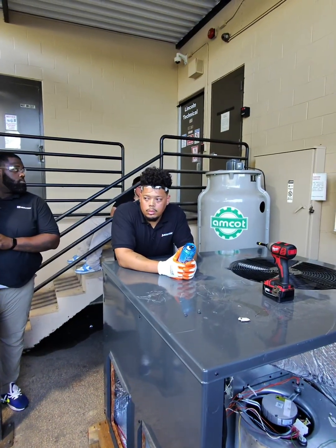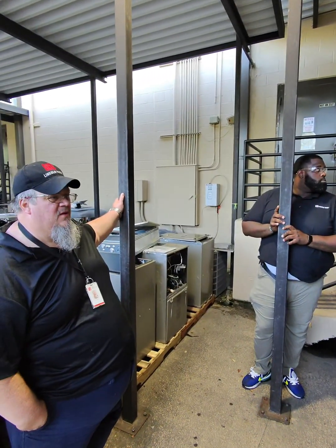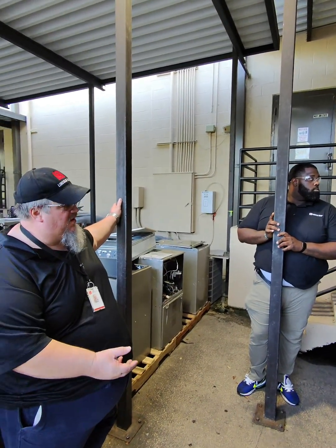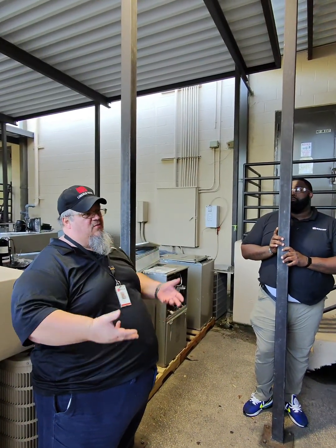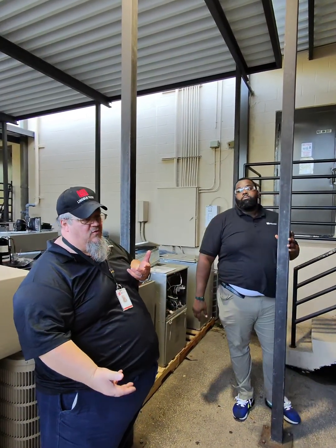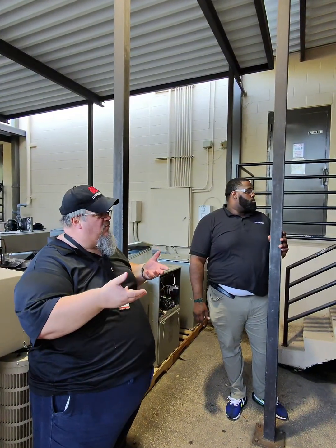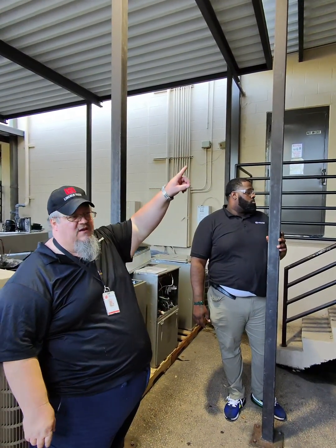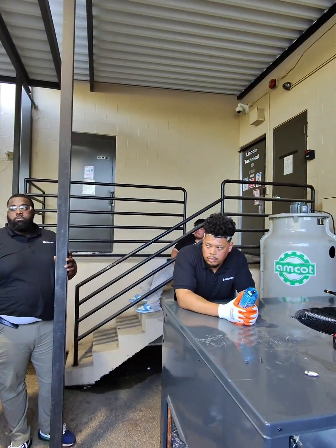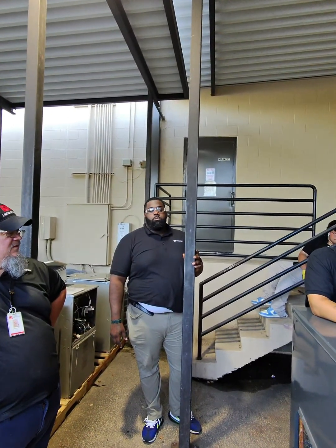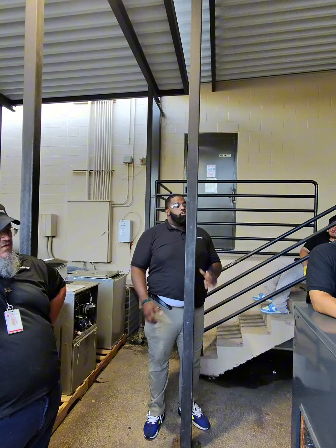Yep. The water comes in on the top. We're pulling air across the bottom, pulling it up through the fill. When the air comes across the fill, it's cooler than the water temp. It cools that water down and discharges the heat out the top. That's all it is. It's just a fancy condenser. We're using water instead of refrigerant.